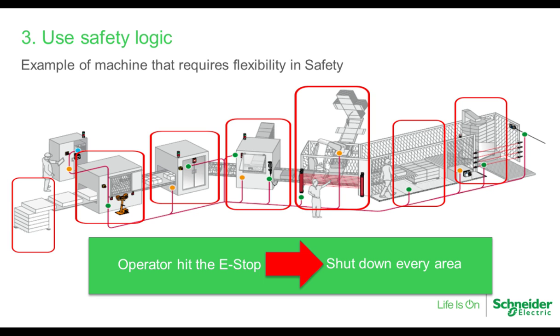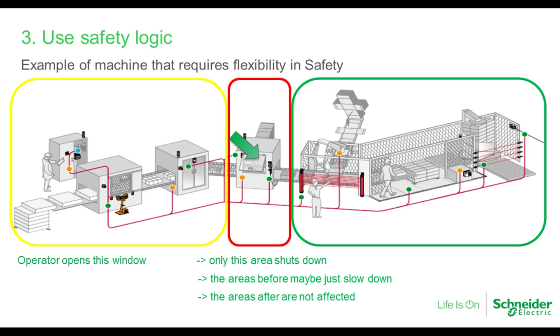and I'm not saying this is a rule, but typically you're going to shut everything down that's associated with it. And that's because if a person's hitting that e-stop, you don't really know where the problem is. Somebody said help, and somebody else said stop, right? So you shut all the associated equipment down. It's the right thing to do because you don't know how to isolate it.